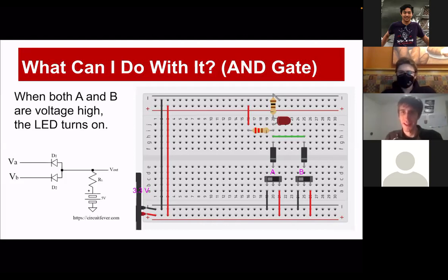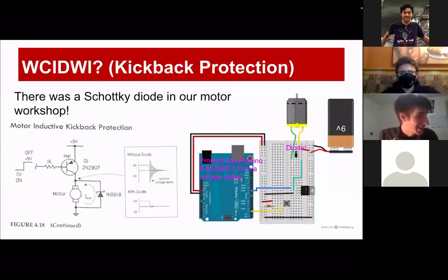LEDs are light-emitting diodes. That's why they have an anode and a cathode, and they only work if they're going one way, only if there is forward biasing from the anode to the cathode. And that is also a good example of diodes just blowing up if you add too much current, because LEDs blow up all the time. At least I personally blow up LEDs all the time. I don't know if you are some magic man, but let's see.